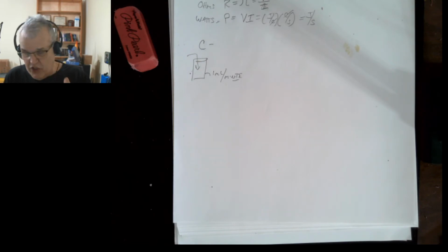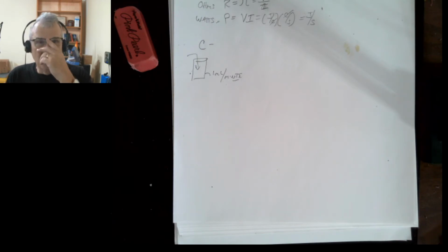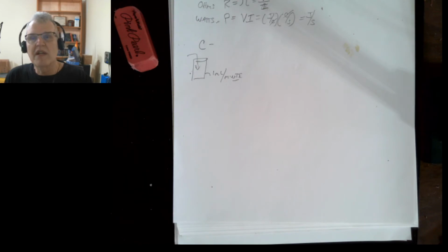So, capacity is from the state of charge. If you go from the 100% state of charge, fully charged battery, down to the cutoff voltage, that's typically what it's called, the voltage at which you will stop discharging the battery so that you don't cause damage. 18650 batteries, generally the top end's 4.2, the bottom end's around 3 volts. Okay, so that would be taking it from a state of charge of 100% to 0%.